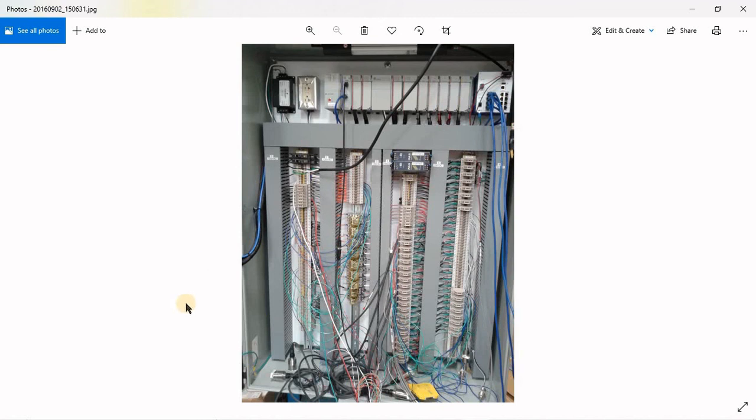If you can see here, we have this cabinet. During testing, we have a lot of cables, because when we did the testing, we connected to a cabinet with all the I/O, so we can simulate the compressor or the turbine which is running, and we make sure that everything is going right. The only thing I showed you here is the distance between the terminals and the space allowed for the wire in the cabinet, because that's something specifically for the maintenance guy: it's easy or hard to do the maintenance for the cabinet.